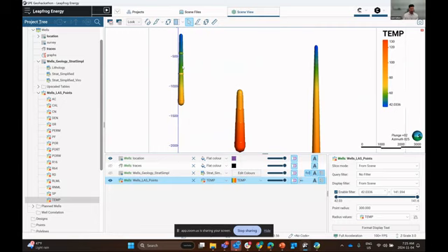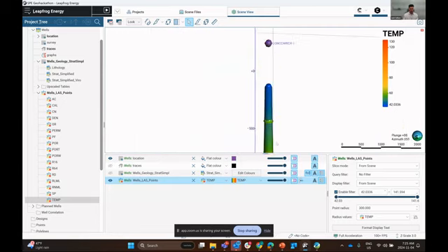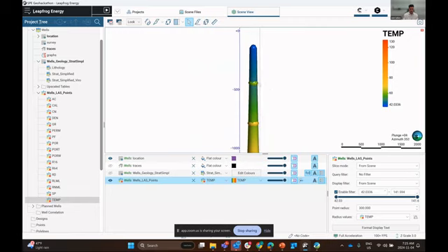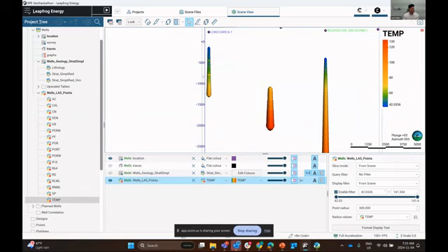This is also going to allow you to start to visually QC these objects. So in this particular well, you might want to remove these 2 values because they seem to be outliers in this particular log. The other 2 look quite good. So again, it's utilizing Leapfrog to visually determine outliers and also potentially spot some trends associated with your data.